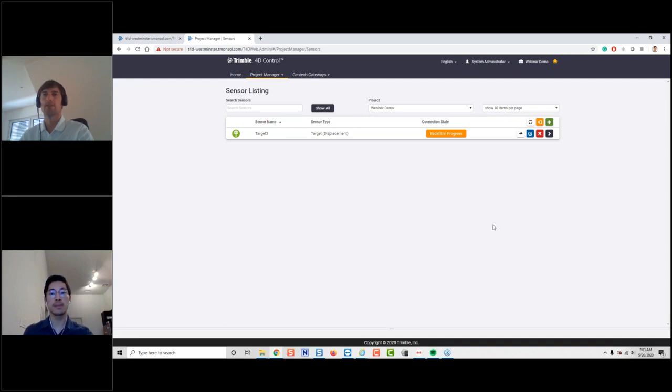We have full support for the coordinate system manager, as you might know it from TBC, for example. So you can do a default local coordinate system, but you can also select any public coordinate system which is officially supported, or which is out there. You can also do a site calibration, so that's also possible. So all of this is supported.